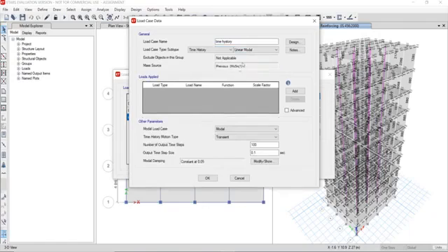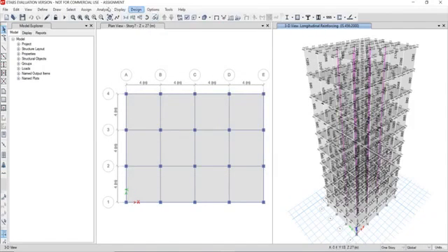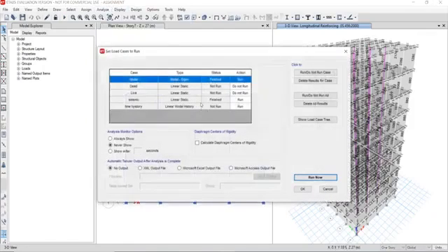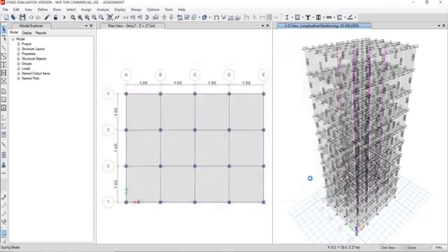Go for time history analysis. Add our load applied in acceleration load type, its load name is U1 and function is our given time history function, and scale factor is 1633.5. We already saw, and we only have the X direction, so no need to add another load case. So then click OK. Click OK. Everything got assigned, and now analyze. Set load cases to analyze, as you saw in the previous type. Now click run now.